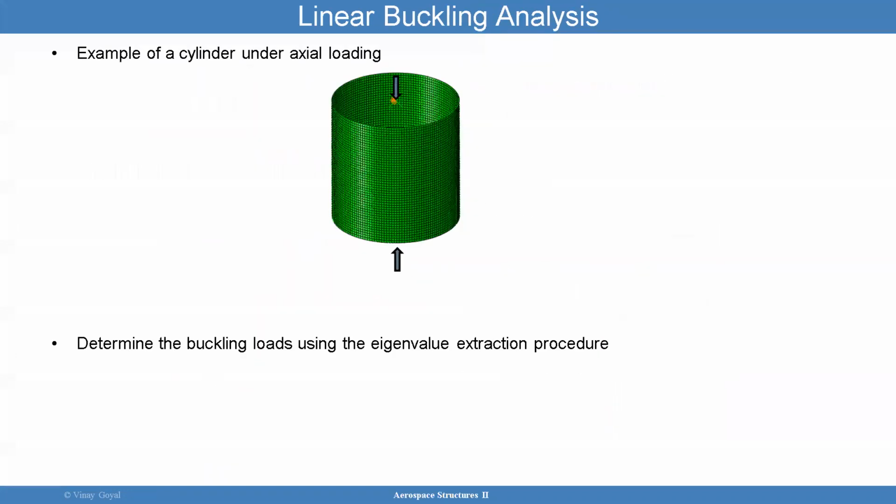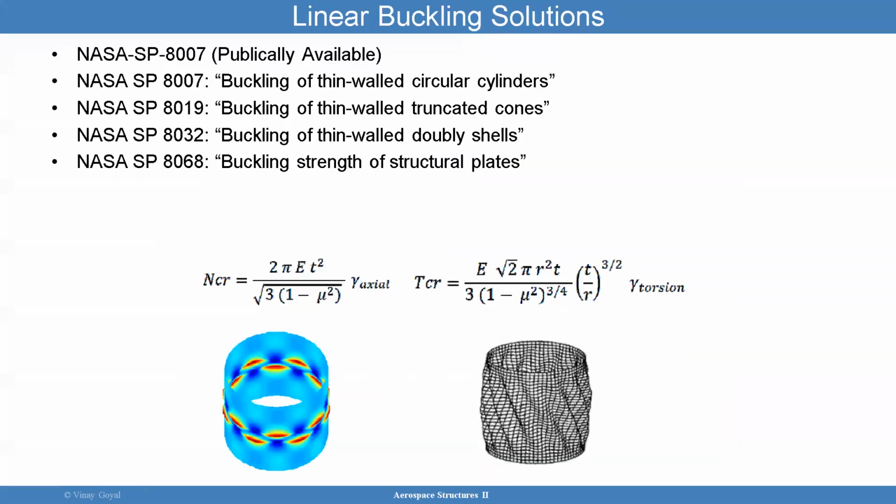We're going to claim that when you do the linear buckling analysis, Abaqus will produce these mode shapes. We're going to claim that if the mode shapes happen to be the imperfections that we have, it should be much easier to buckle if the mode shapes were of that kind.